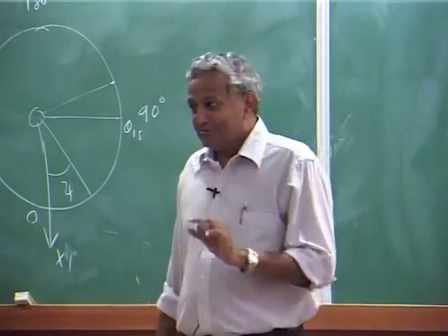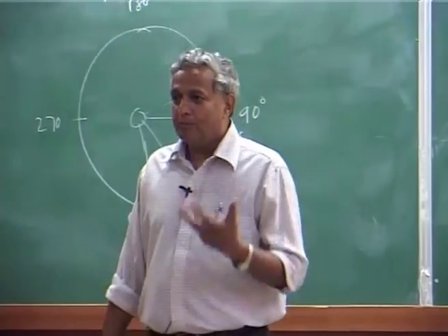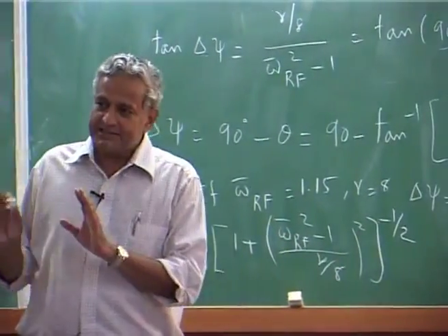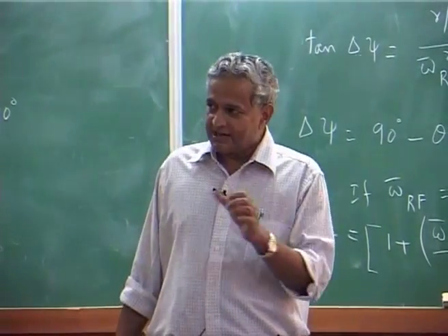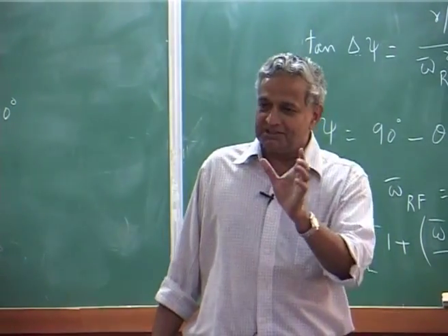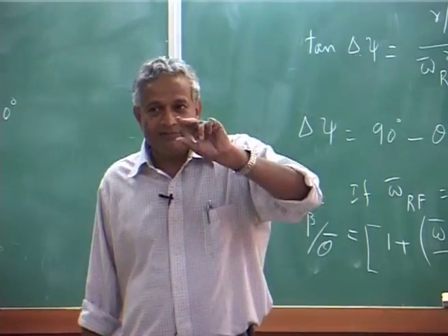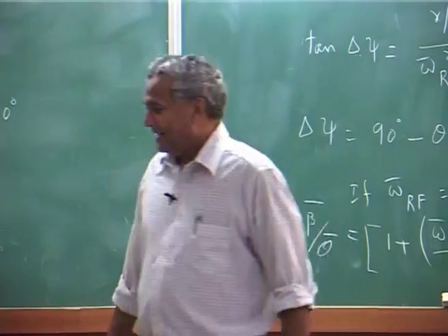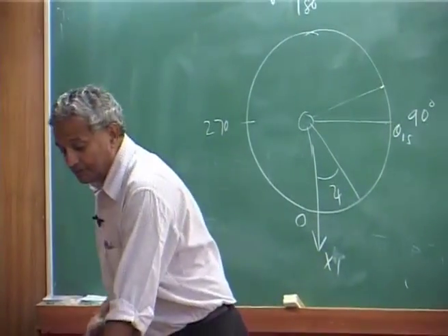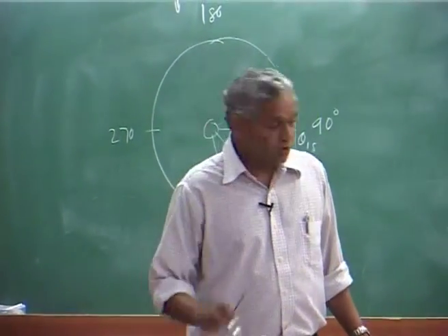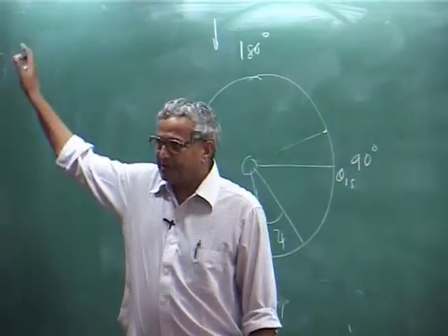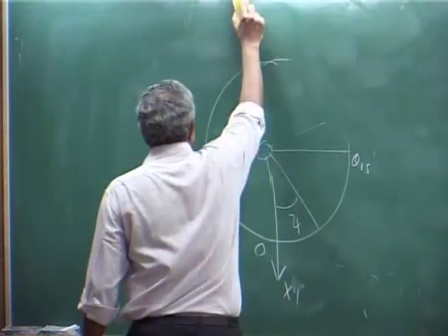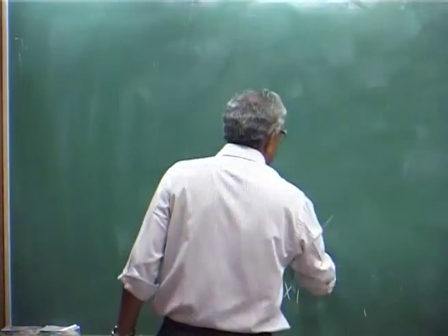But then the problem is, now what we are going to discuss is what happens to the hub moment. Because till now we have studied thrust, side force, longitudinal force and the torque. I said we would keep the hub moments for later. Now, let us look at the hub moment which arises due to the flapping aerodynamics. I would call it the flapping motion, because you have to take the inertia also. Now, how do you get the hub moment?